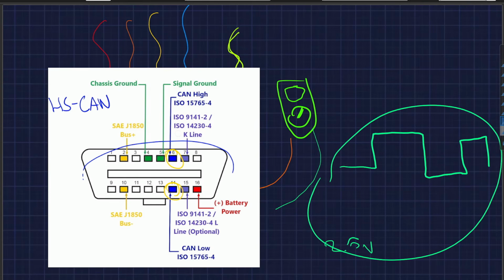If you see a wire sitting steadily at 2.5 volts or fluctuating up and down by roughly 1 volt, the odds are very high that you are staring at the CAN bus.